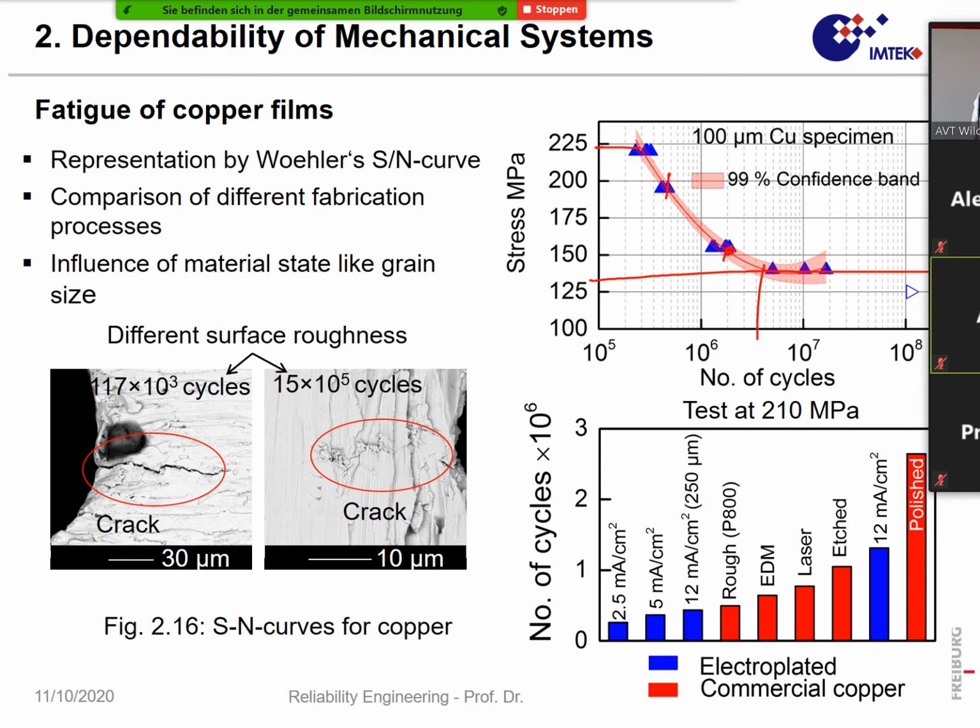So that would mean, for instance, if we test to half of it, that would be 50%. And here, we go to half of it, so it would be 50%. So if we test to 50% here and 50% here, we would have to expect that it will fail. And that is the so-called life fractional rule.